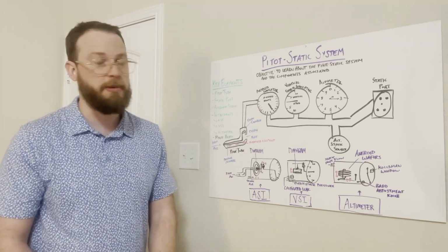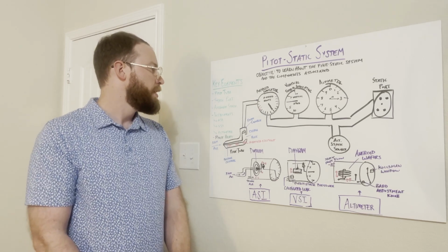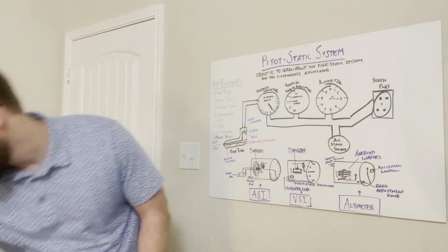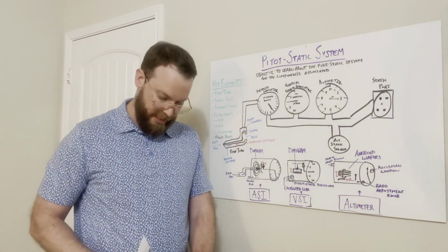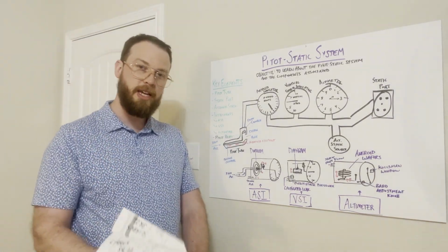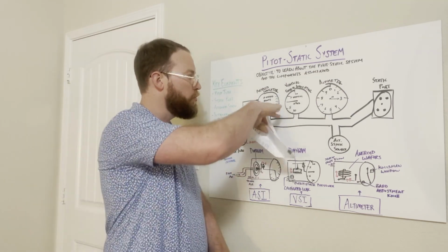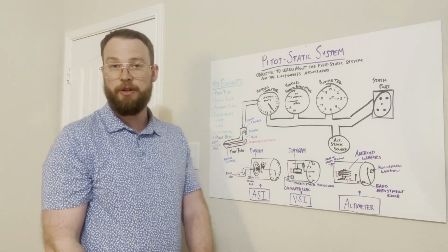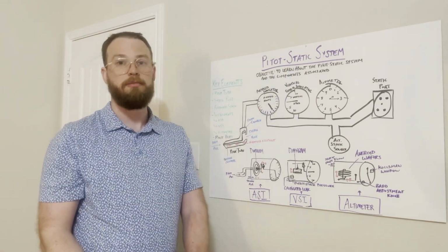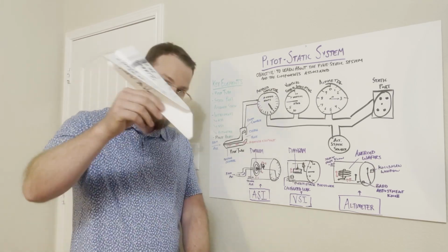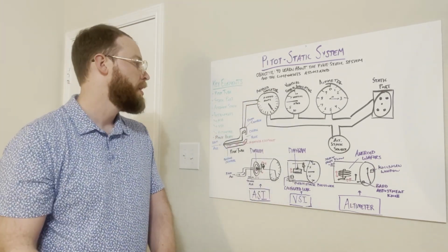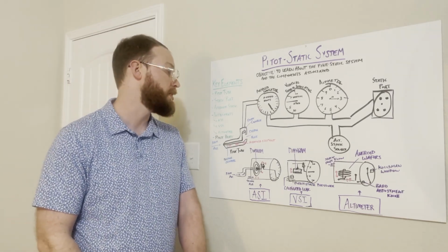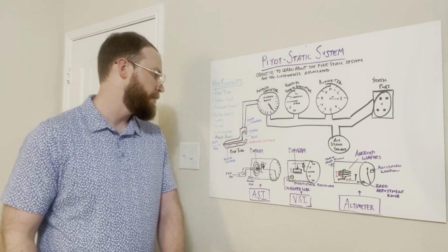Now going to our vertical speed indicator, VSI for short, it tells us where we're going in relation to up or down. So I have my mini Cirrus SR22 here. As we increase feet per minute, it's going to move the needle higher in 500 feet, 1,000, 1,500 feet per minute ascent. Or if we're going back down, descending here, it's going to show 500 feet per minute, 1,000 feet per minute, or anything in between as far as whether we are ascending or descending. Now back to our diagram here.